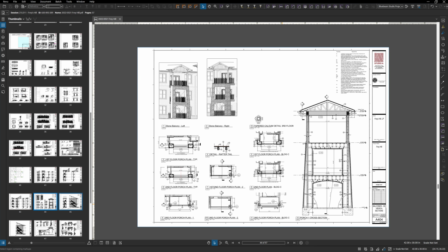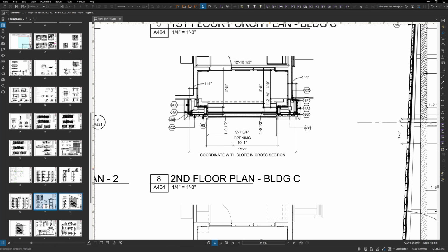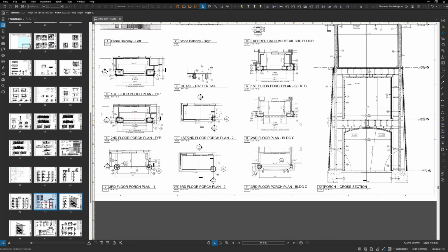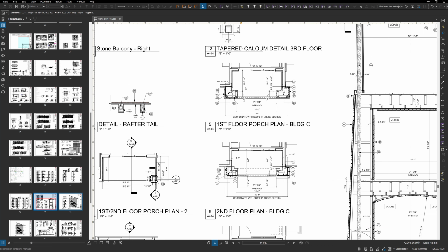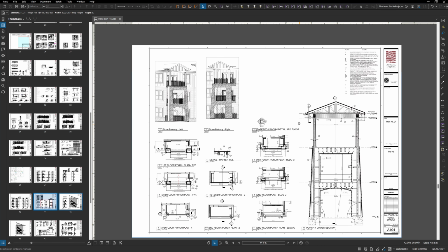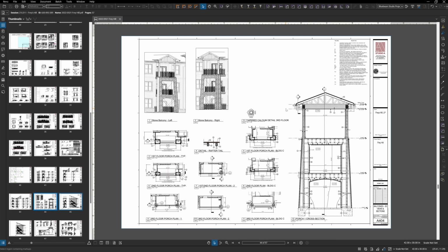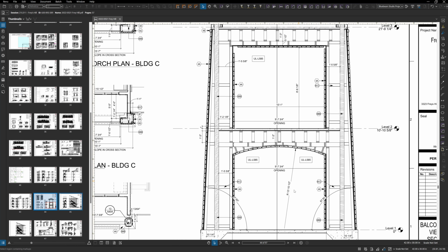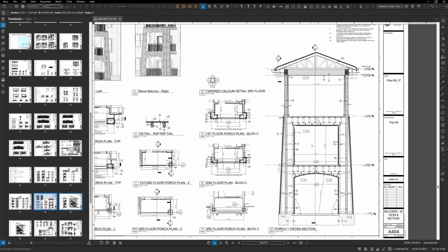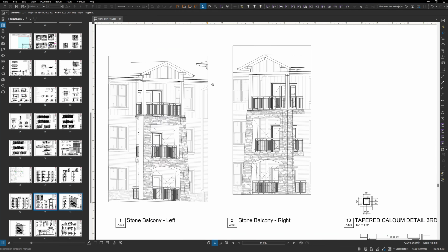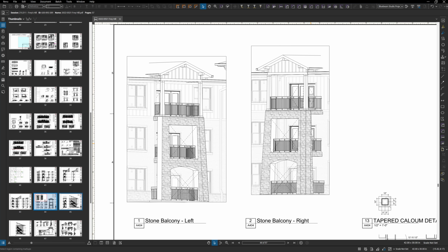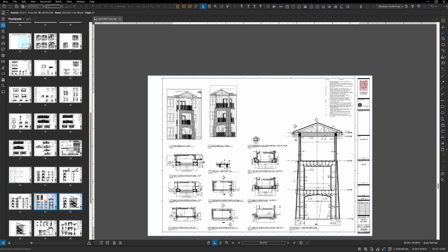This sheet in general, when you're building complicated porches, it's really important and very helpful to build a series of details with a lot of good dimensions for where the structural column is, and then the furring, the decorative wrap around the column that you want to create. This sheet does a nice job of covering that, showing how they do the arch, the radius of the arch. It's all fairly well documented. They even went so far as to provide a couple of isometric details, just some views so the contractor can understand better what he's trying to build, which is really nice.